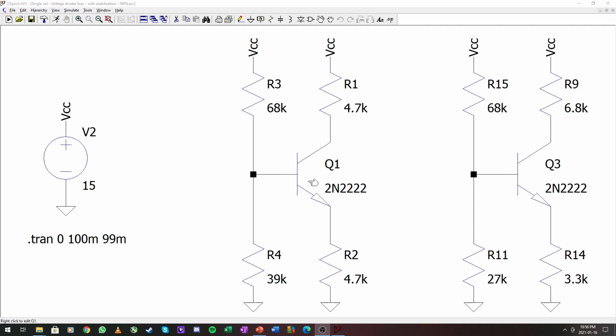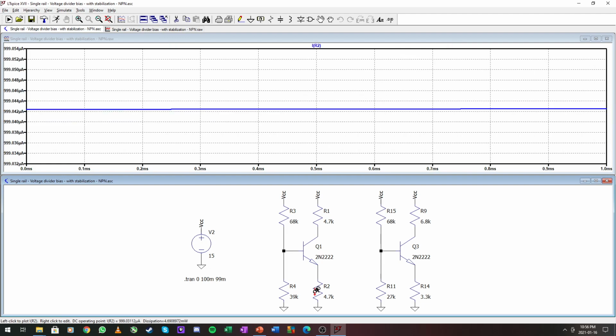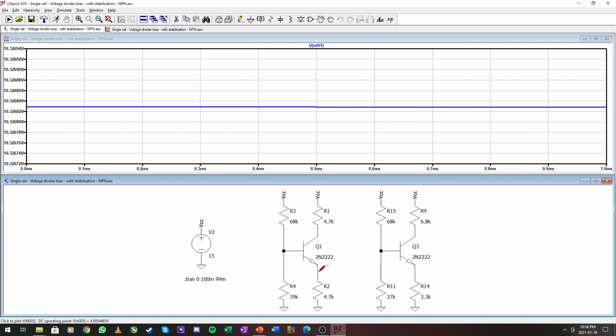So here are our two solutions implemented. Let's run it. Here is our emitter voltage. It is less than 5, but we used the 4.7K, so that is close to our design values. There is almost 1 milliampere flowing in there. Same here at the top, minus the base, but 5 microamps. So we did reach our specifications, all 3 of them here.